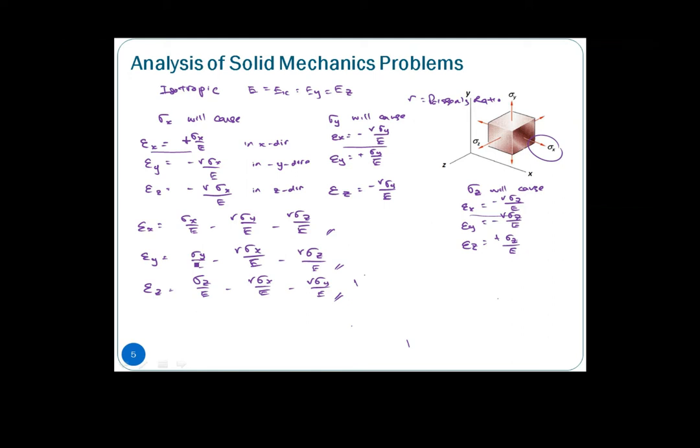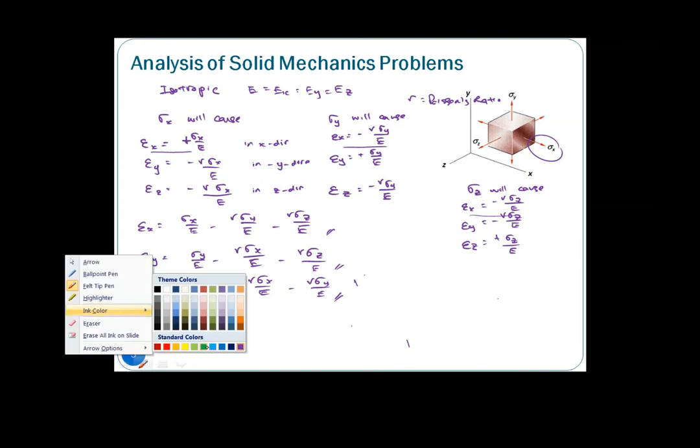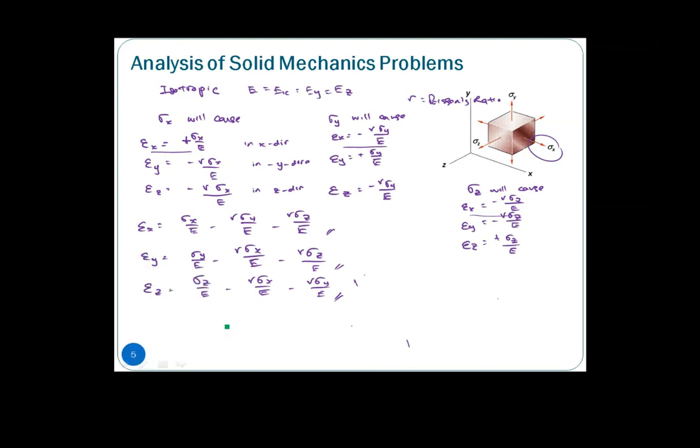So just now we have, let me use another color. We have our equations under plane strain, right? So we have this, okay? Under plane stress, we do not have these parts. Plane stress, this part is gone. No contribution from the Z axis. But under plane strain itself, epsilon Z is equal to 0, but we still have contribution from the normal stress in Z. So that is our so-called plane strain equations.